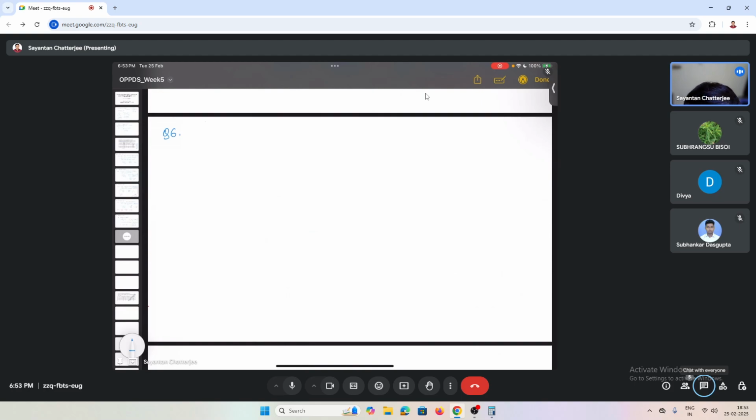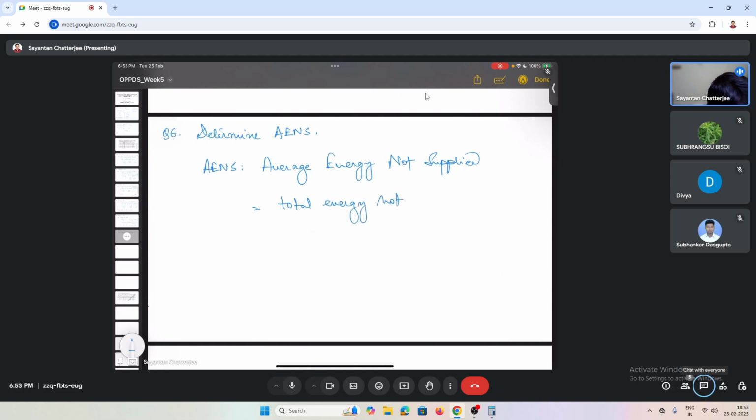Question 6. Question 6 is determine AENS. So what is AENS? Already ENS we have written. This is average energy not supplied. Okay. So total energy not supplied we have already calculated, that is ENS. Total energy not supplied divided by the total number of customers.